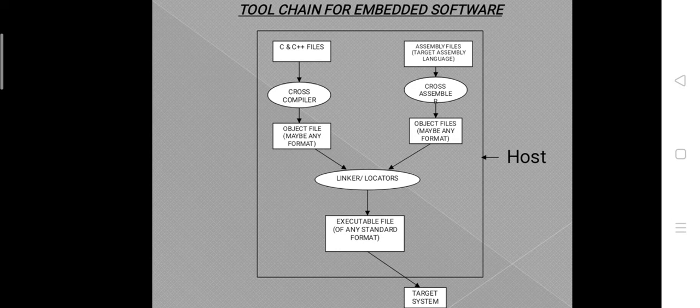Then such files are given to the linker, where all other sub components of the program are combined and located. So the linker will generate a machine code. This machine code is given to a single executable file. So this would generate a hex format, or you can say the image, a single executable image that can be burned on the ROM of any processor or controller.